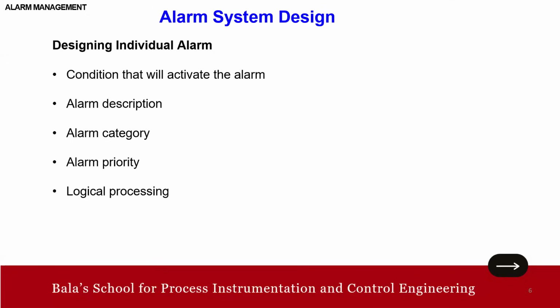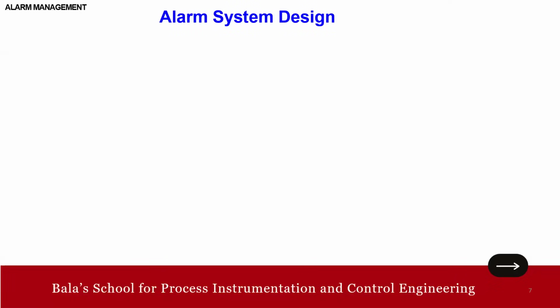Then logical processing. So once designed, it should be checked to confirm the alarm will actually support the operator. So that is the point, right? Okay. And another point is a particular concern is whether the alarm configured will actually give the operator enough time to respond. So that also matters a lot when we design an alarm. Okay. Now the last for this session.